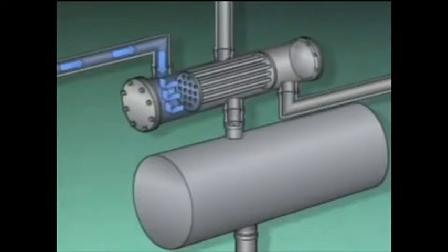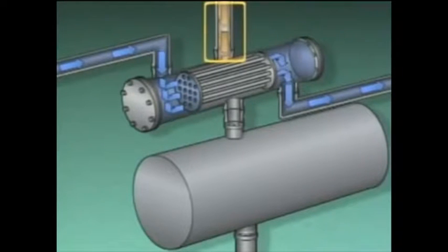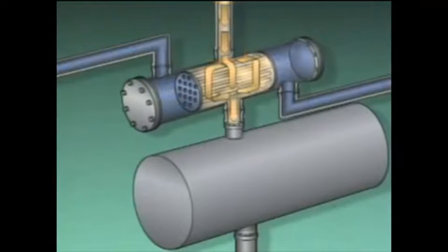As a result, the cooling water is heated and the vapors are cooled. This causes the vapors to condense on the tube surfaces. The distillate drips off the tubes and flows through the distillate outlet to the receiver where it collects. Refrigerant can also be used as a cooling medium. Like air and water, refrigerant absorbs heat from the hot vapors.